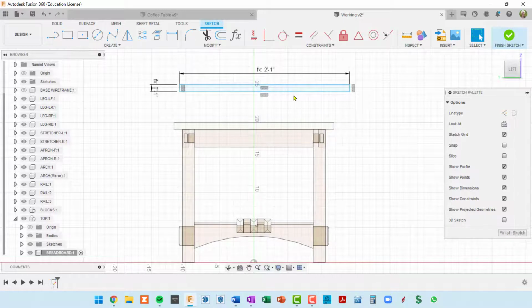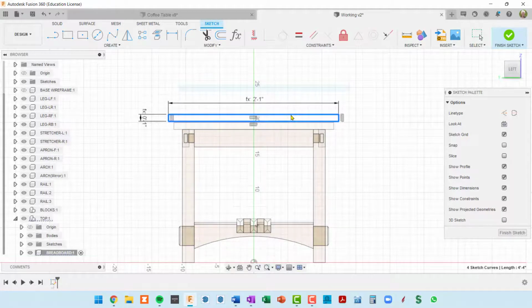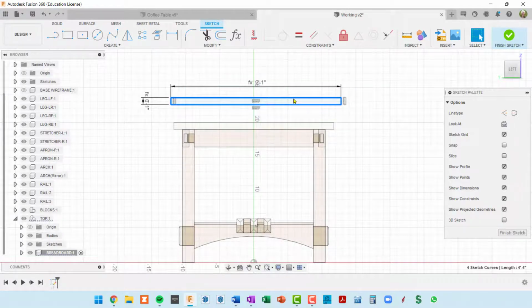All right, let's position this rectangle manually and see that's what we want. So that breadboard, I think it overhangs by 3/4 of an inch on each side. We want this to align to the top. We can use a coincidence to do that. Actually, we're going to use a collinear setting here. We're going to say the top piece of the rectangle is going to be collinear with here. Let me correct that. I'm not going to do that because that would bring us down here, but then we'd also have to center it.